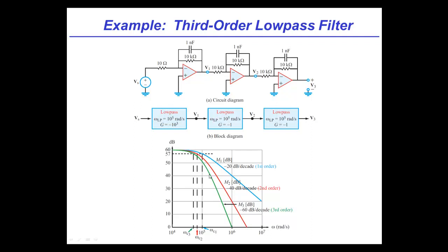Now notice though, just to be completely clear, each of these has the exact low-pass cutoff frequency independently, but together they are in fact shifting the combined cutoff frequency slightly as well. The 3 dB point for the combined thing is here, but if you go back to the original curve, it's much lower. So in other words, you're also shifting the corner of the combined thing. Right, and that makes sense because the 3 dB point falls within the shoulder region, so it would make sense for that to happen.